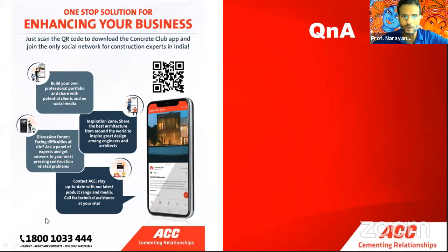Calcium hydroxide is low. What could be the effect on carbonation? Carbonation reduces strength and induces shrinkage. Good question. If the calcium hydroxide content is low, you will have carbonation. But again, remember, carbon dioxide also has to diffuse through the concrete. If you make a really, really dense microstructure and make diffusion much slower, CO2 also has no way to go. So again, I keep telling this point all the time. For UHPC, microstructure is the key. You get it as dense as you possibly can. A lot of problems will go away.